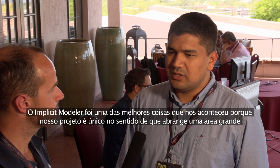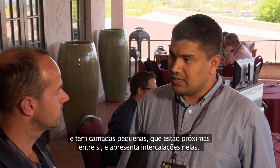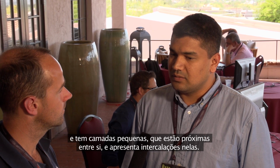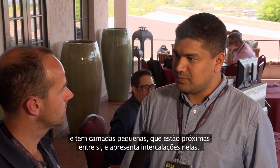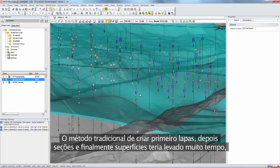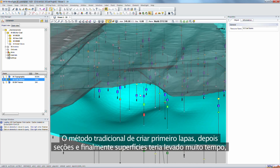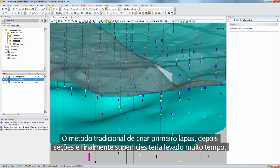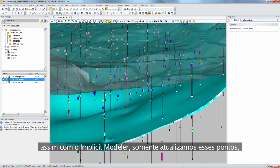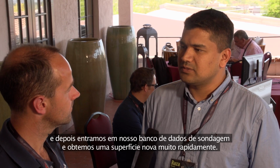Implicit modeler was actually one of the best things that ever happened to us, because our project is unique in the sense that it's a big area with small seams which are kind of close together and have partings in them. So for us, we are constantly updating our model, and the traditional way of doing footwalls and then doing sections and then creating surfaces would have taken so long. With the implicit modeler, we just update those points and get in our drill hole database and get a new surface very quickly.